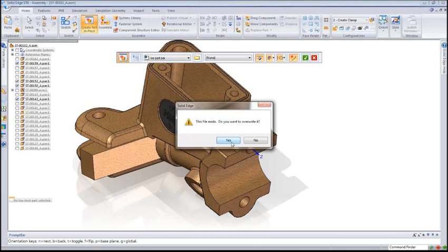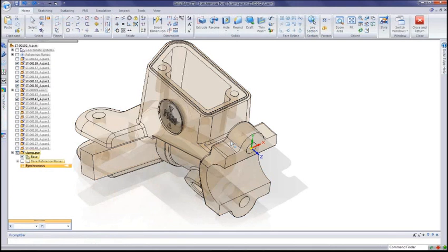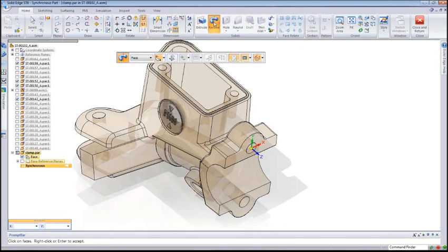Clamp. And it says yes, I do want to overwrite it because I've already made it before. I'm going to say, you know what? I need to make this clamp. Watch what I can do now. I'm going to click on Revolve. You might think, Cecil, we know what Revolve is. But what you haven't seen is this. Now, I'm going to use something called include, or I should say exclude internal face loops.